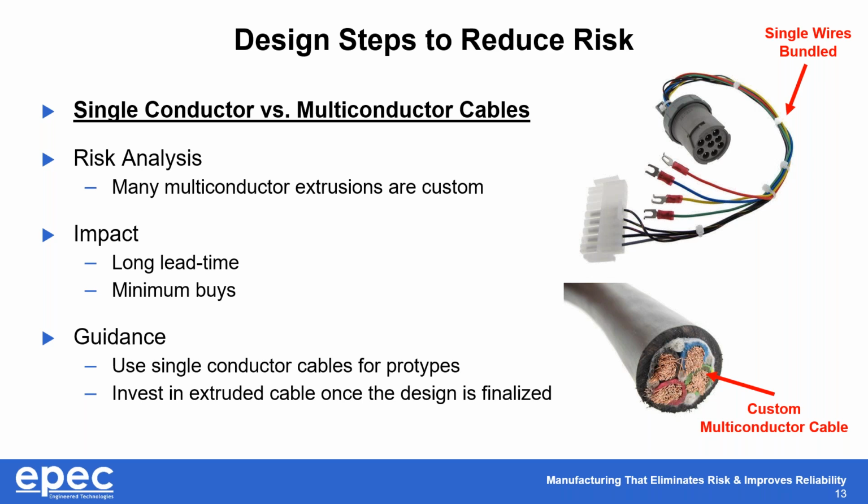But if you need 10 prototypes and you need them quickly, and you're not sure if they're even going to work, there is very little value in spending the time and money for a custom extrusion if you're doing fit checks or some type of preliminary testing. Electrically, we can run a similar number of conductors and bundle them together to achieve a similar multi-conductor construction. So this cable in the upper right and in the bottom right here, although they look completely different, they both use conductors that are bundled and run in a certain configuration to meet design objectives.